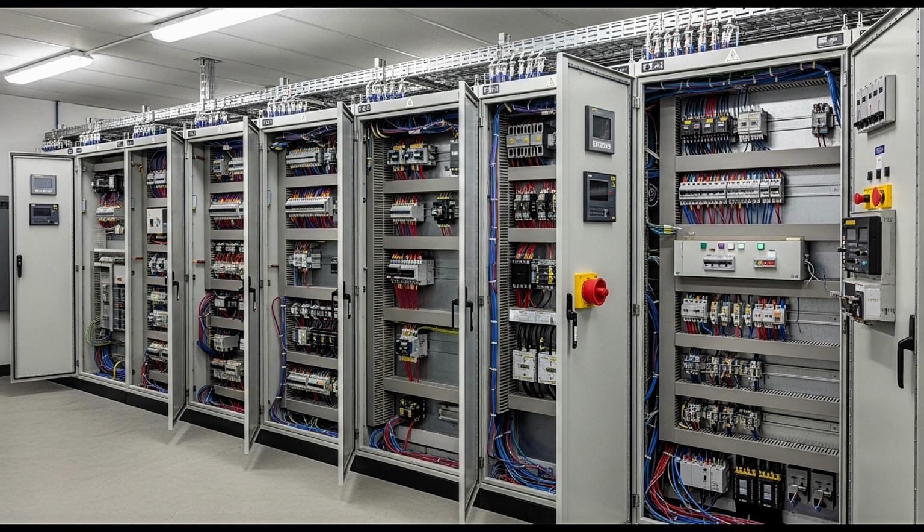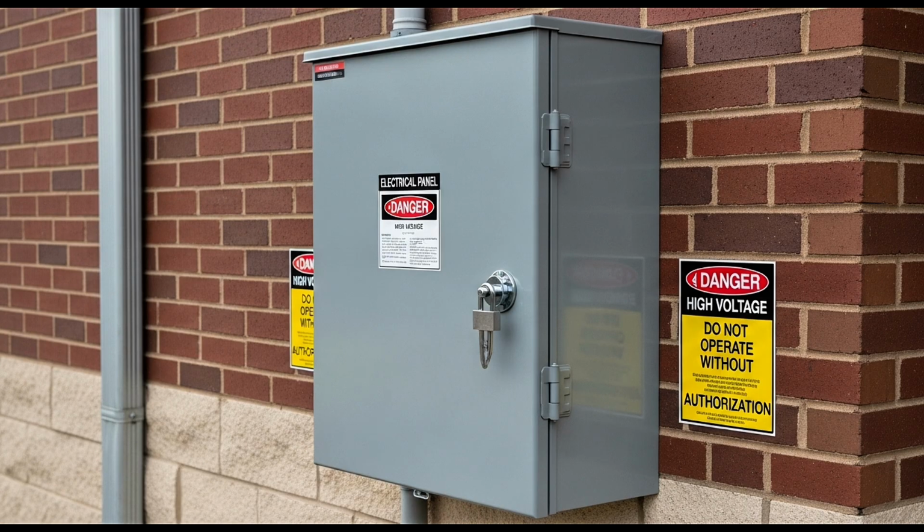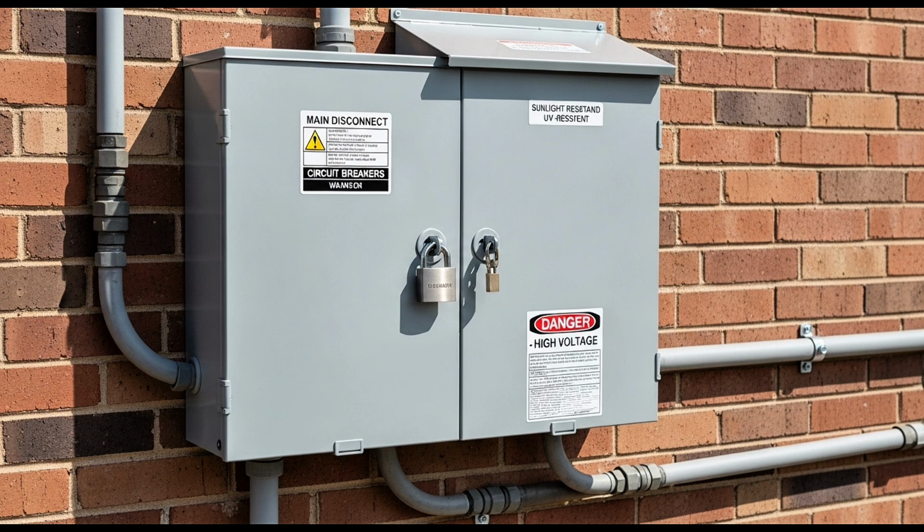But when something goes wrong, say a wire insulation fails and touches a metal box, the ground wire provides an immediate, low-resistance path for fault current. This current surge is large enough to trip the breaker instantly, de-energizing the fault before someone can touch the electrified surface. Safety, maintenance, and modern innovations.